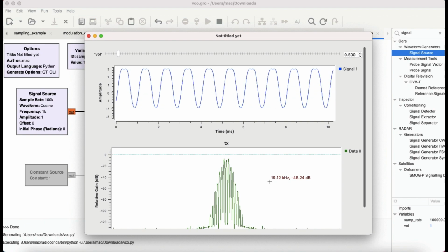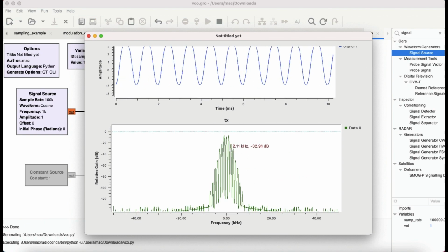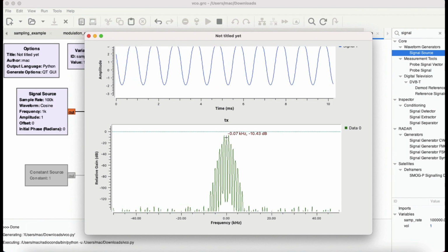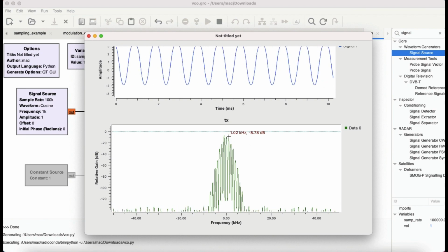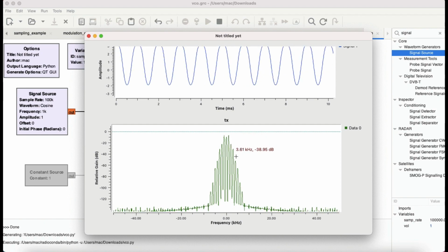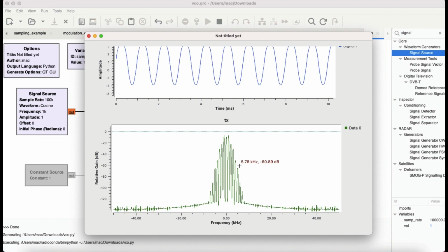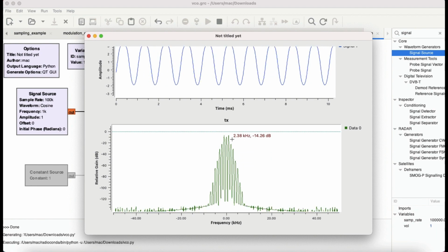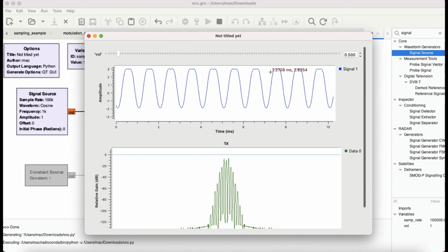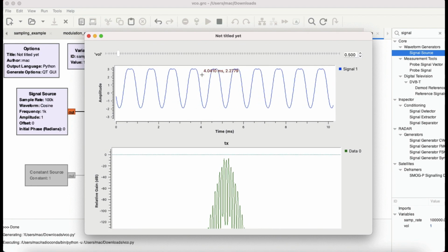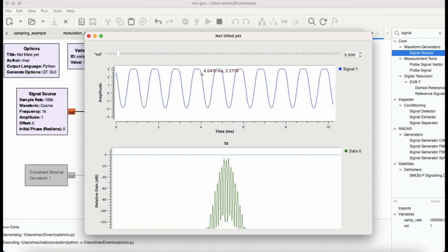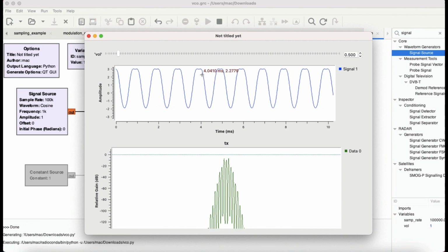Now, when I closely look at the spectrum of this, doesn't it look something similar to an FM signal, where you have your carrier frequency, which is at around 0, and then some values FC plus FM, FC plus 2 FM, FC plus 3 FM, and so on. Because the frequency spectrum of a frequency modulated signal is actually like this. So this is just to show you how you can use a VCO to generate variability in your frequency based on whatever the input voltage is.